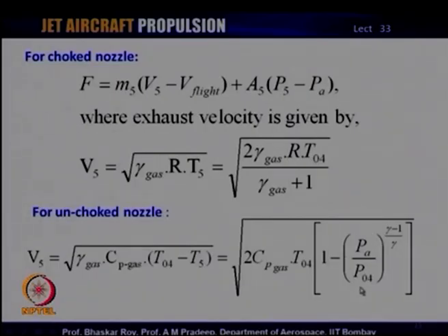That means, assuming that the nozzle finally exhausts flow to the ambient at ambient pressure. That means maximum acceleration or maximum change of velocity through the nozzle has taken place down to the ambient pressure, and this is the unchoked nozzle that one can get without getting choked.